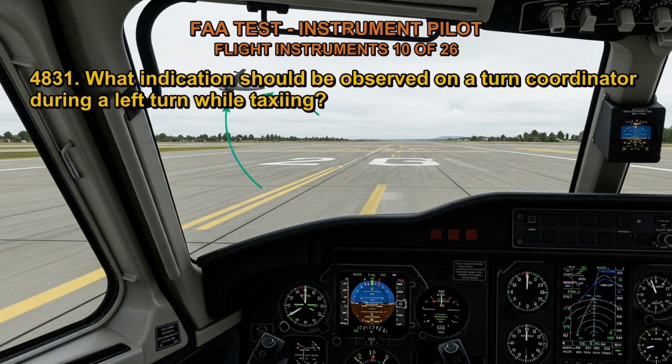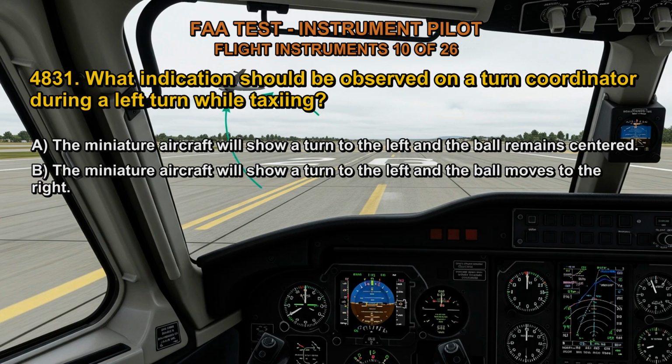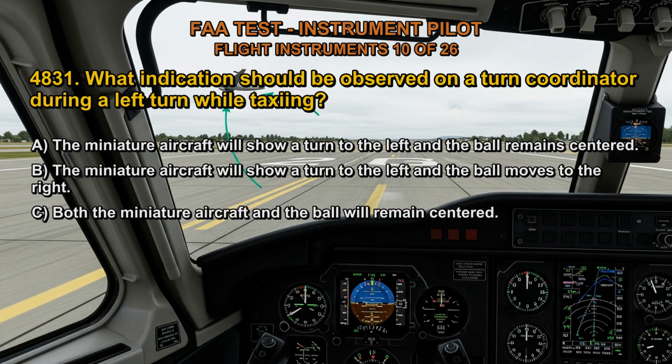4831. What indication should be observed on a turn coordinator during a left turn while taxiing? A. The miniature aircraft will show a turn to the left and the ball remains centered. B. The miniature aircraft will show a turn to the left and the ball moves to the right. C. Both the miniature aircraft and the ball will remain centered.